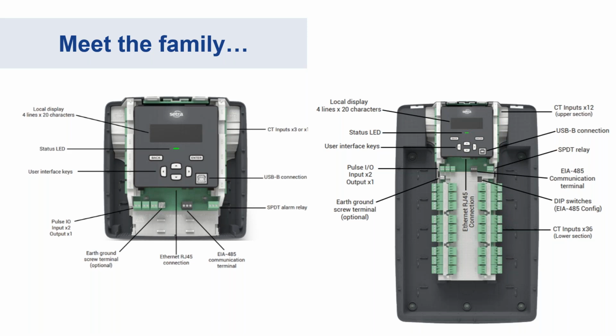Can the meter be set up to automatically download data on a set frequency for backup? So is there some sort of backup control that you're aware of, Mike? Again, this might be a question for our product management team or our technical support. Yeah, so as long as the meter is on one of the networks that supports IP, BACnet, or Modbus protocol, you'll be able to pull the data from the meter itself.